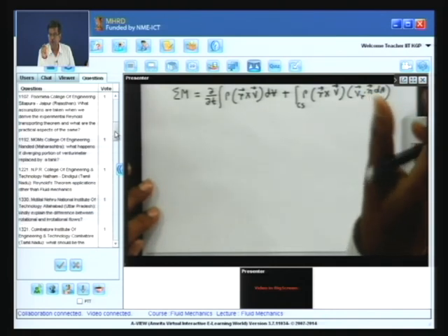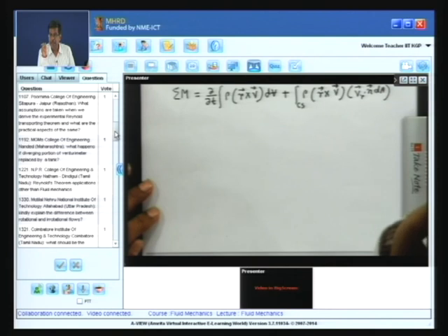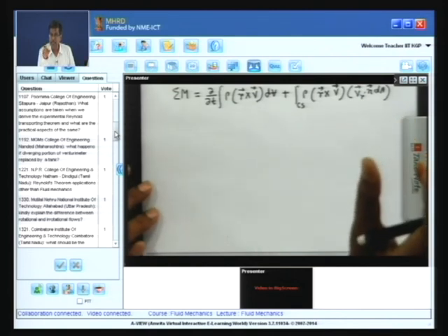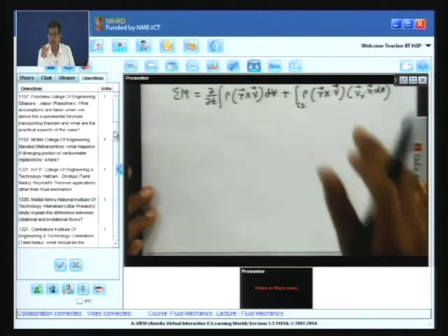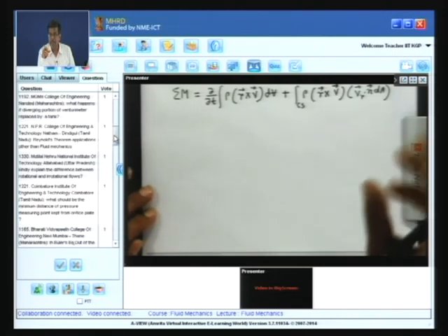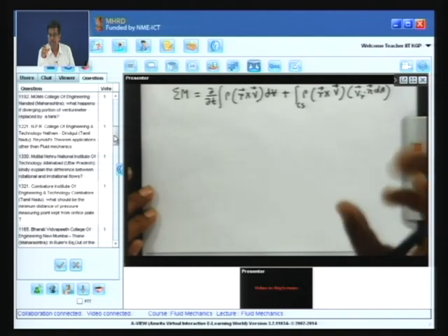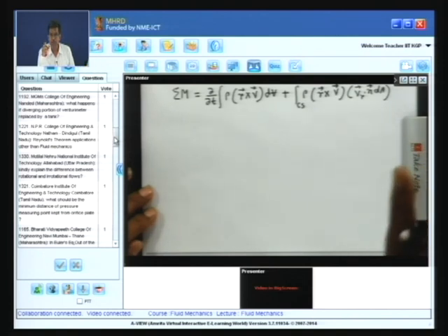For example, the flow rate can be found by multiplying velocity with area and density, where the velocity is the relative velocity, that means velocity relative to the control volume. And in many cases we are concerned with linear momentum only, with a rectilinear motion control volume, for example the jet engine and the rocket I told you about yesterday.